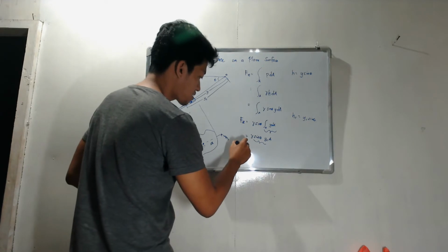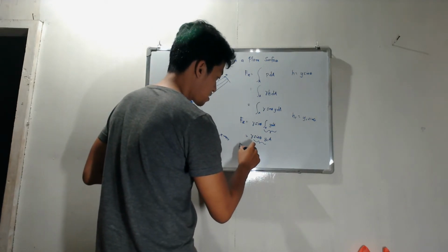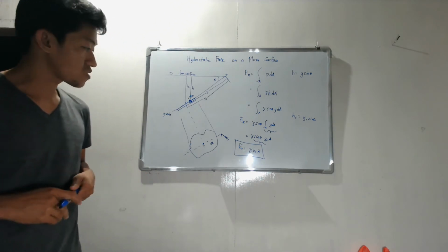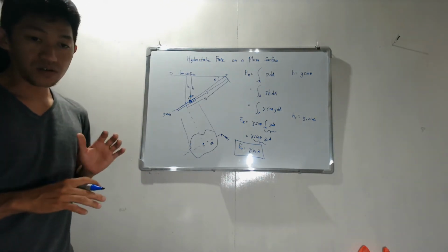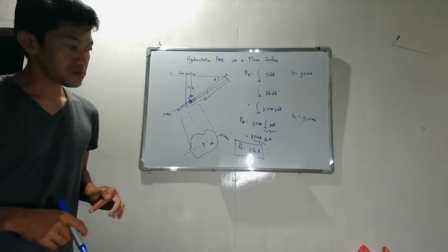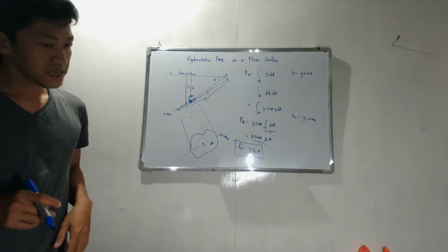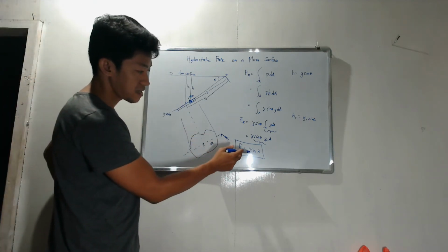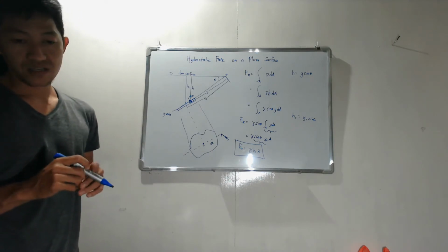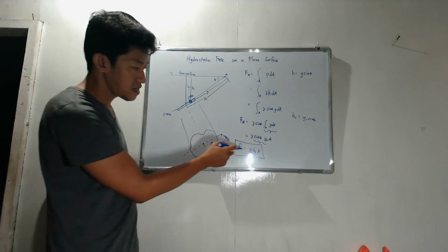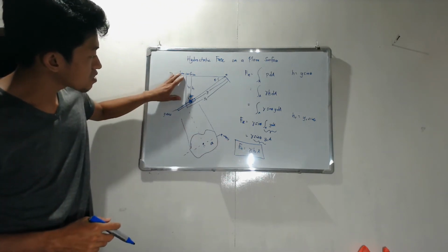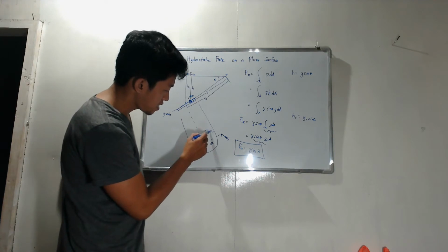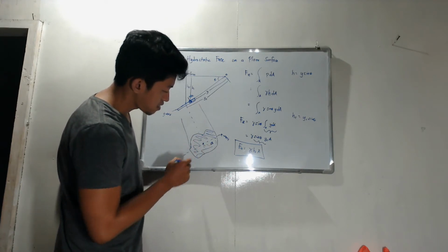So therefore the resultant force is just gamma h sub c times A. If you have the dam and you want to know the forces acting on the surface of the dam, you just multiply the gamma, which is equal to rho density times gravity, multiplied by the distance between the fluid surface and the centroid, times A. The area is the area of the surface. Okay, that's it.